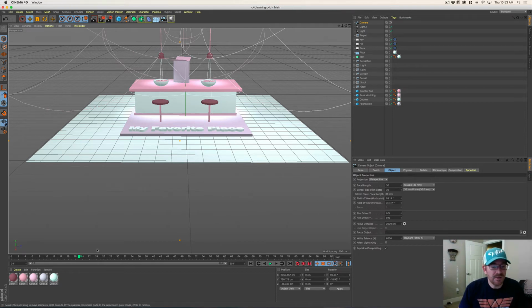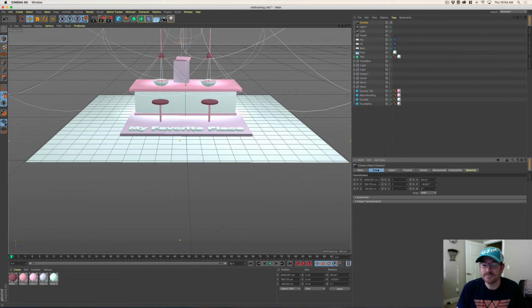So let's go ahead. Now you've got to make sure that you're at frame zero, to set your initial starting point for your camera. And you guys haven't seen any keyframes yet, but they're hidden. They're everywhere once you see them. So we'll need to set our initial state for our animation. Animation works a little differently in this program. So first, you click on camera. Second, make sure that you're at frame 0. And then you're going to go into the coordinates of your camera.